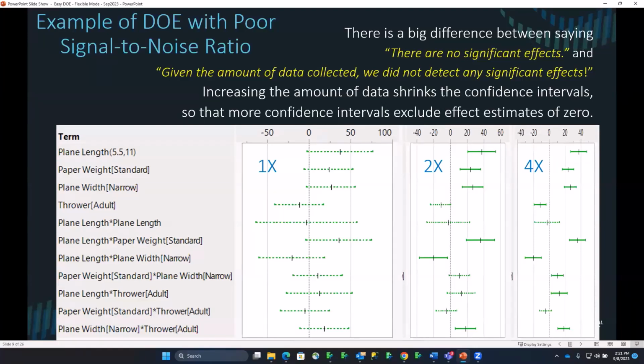You'll see people doing tensile strength measurements. They always do sets of 3 or sets of 5 when they do these pull strength tests, because they know there's a lot of noise in the measurement in that system. So this is an example where one of the solutions would be, let's take more data.